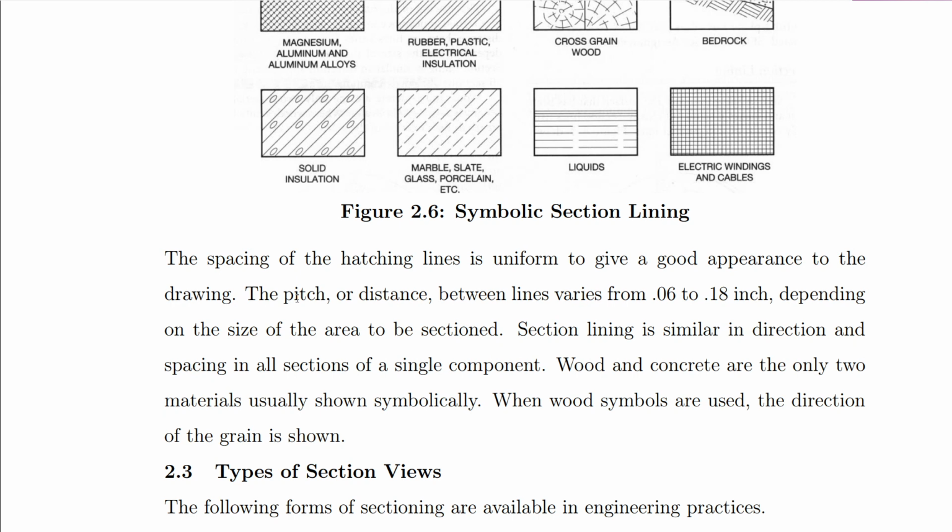Section lining is similar in direction and spacing in all sections of a single component. Let's say that you have a single component, not an assembly.